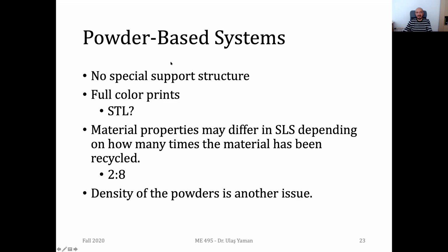These are just an introduction, and we are briefly discussing the design and the fabrication pipeline, the variations in the pipeline. But as we have seen up to this point, there's not much difference, almost the same. Your design, convert to STL files, send to the machine software, do some settings and print. But obviously, if your printer has many capabilities like color printing, you need to have an extra step like coloring your design or doing some modifications on your design.